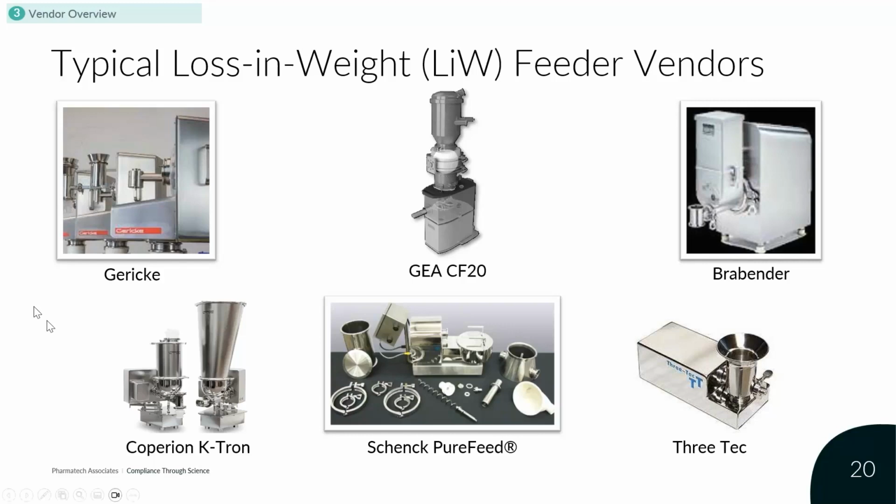is very important for precise and accurate feeding over a long time, because we have a continuous process which we want to run as long as possible without interruptions. So here the feeding of cohesive or electrostatic material could be a challenge. Or if you have, let's say, MUPS applications with very fragile granules, there is a lot in these material characteristics which you have to discover. And yes, this loss in weight feeder again is the heartbeat of the system. So you have to serve it in the best possible way.